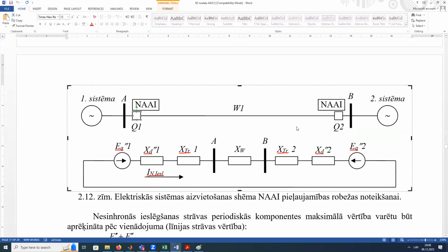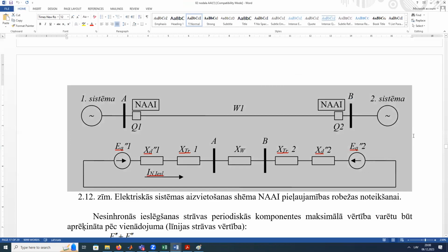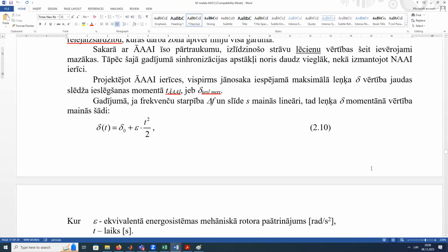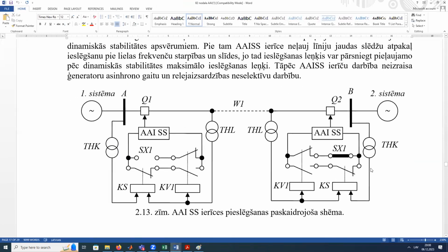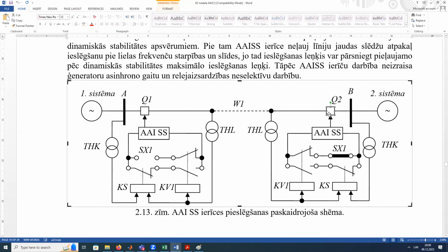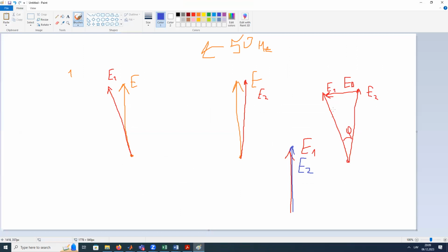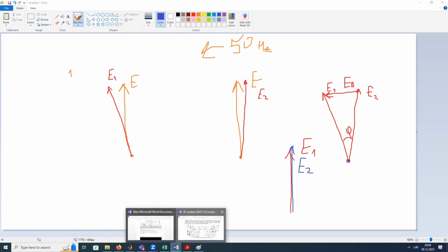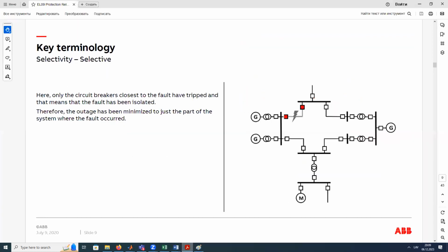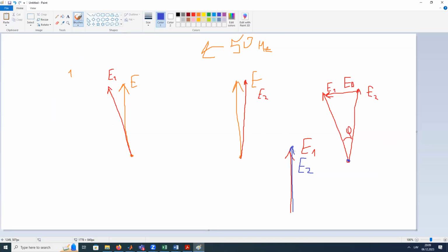That's why reclosing for these two sides operates a little bit differently. This is a little scheme of how it operates. First of all, we connect only one breaker back, to get voltage here and from here. And we are monitoring these two vectors and give the command to connect the second one only when they are synchronous.